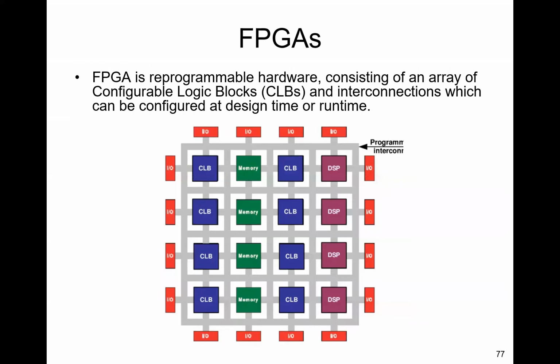So FPGA is reprogrammable hardware consisting of an array of configurable logic blocks and interconnections which can be configured at design time or runtime. There are CLBs, memory, and DSP blocks, and I/O on the sides. So you can download the bitstream either offline at design time or even at runtime to reconfigure the FPGA to perform a different task.